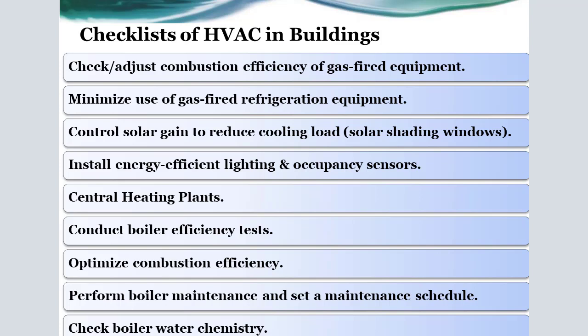This is very important for boiler equipment, using scheduled maintenance and continued review of the operation of the boilers, and also checking the quality of water provided to the boiler in order to prevent leakage and the corrosion effect inside the piping network of the boiler system.